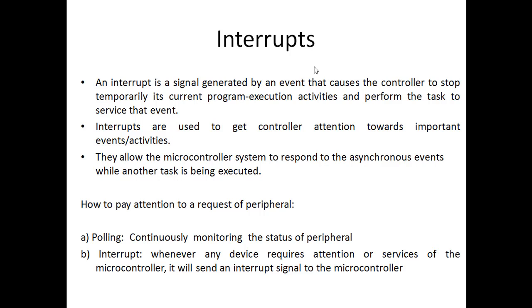Now move ahead. Why do we require interrupts? If we talk about a laptop or a desktop or any smart system, it has lots of peripherals attached to it. And suppose any peripheral requires a service. How will the microcontroller become aware that this particular peripheral requires my service? One way is to use the concept of polling, right? What will happen in polling? Your microcontroller will continuously monitor the status of the peripheral.